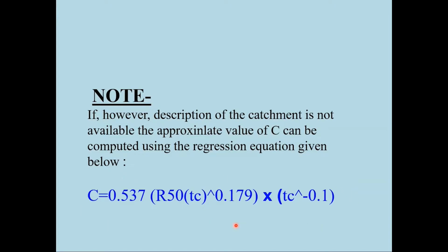But it is better to go by the X, R and F values, because this empirical equation has again used some assumptions to arrive at this empirical relation. So a better result will be obtained if I know the X and F values from the graph or from the table which we have seen above.